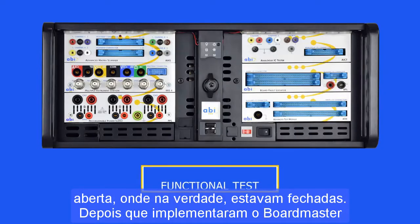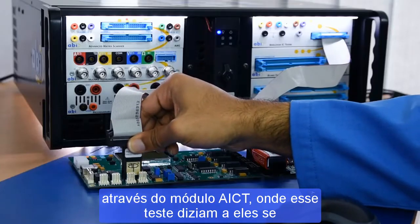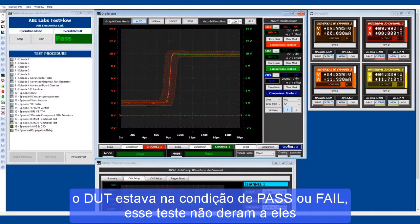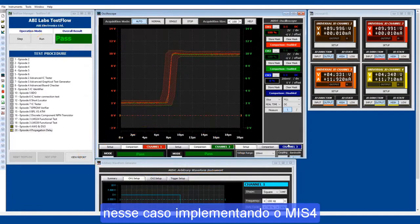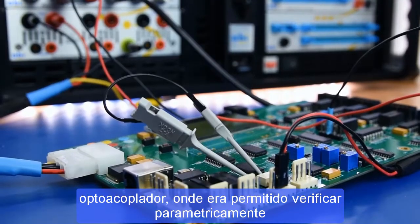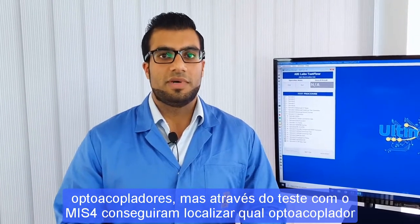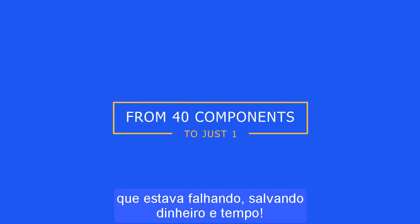Once they implemented the BoardMaster into the repair and maintenance department, they were carrying out a functional test using the AICT module, and this test was telling them whether the device was passing or failing. However, this test did not give them more detailed information like a parametric test would do. So in that case, they implemented the MIS4, which worked out the switching speed, the propagation delay of the optocoupler, which allowed them to find out which actual optocoupler was at fault. They had previously been replacing all 40 optocouplers, but then they minimized this all the way down to the actual optocoupler that was failing, saving them a lot of time and money.